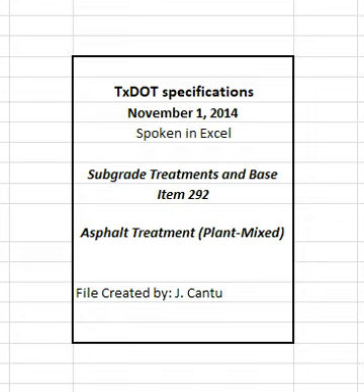2.2.2 RAS. Use of post-manufactured RAS or post-consumer RAS, tear-offs, is permitted unless otherwise shown on the plans. RAS is defined as processed asphalt shingle material from manufacturing of asphalt roofing shingles or from re-roofing residential structures. Post-manufactured RAS is processed manufacturer's shingle scrap byproduct. Post-consumer RAS is processed shingle scrap removed from residential structures. Comply with all regulatory requirements stipulated for RAS by the TCEQ.